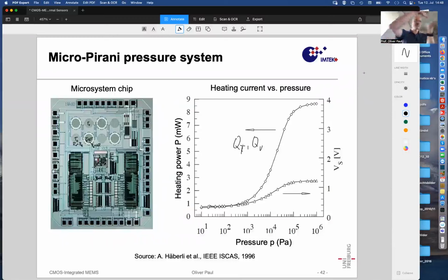Capacitive pressure sensors, where a conductive membrane is deflected by a differential pressure, as we have seen in chapter 2 from Siemens or Infineon and other companies. Those are potentially structures that don't consume as much power, because measuring a capacitance doesn't require heat to be dissipated and lost to the environment.